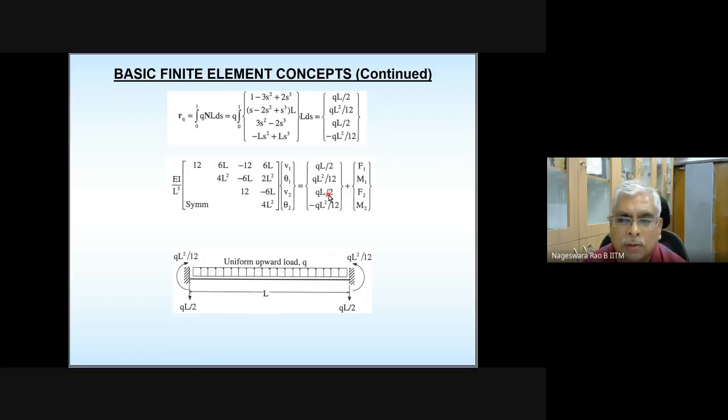If you don't want to do this integration, this vector is going to be the same as treating that particular beam element as though it is fixed, and based on your structural analysis background, you find the reactions at the supports and put those reactions at the supports with proper sign convention as per applied loads and moments, whatever sign convention we are following.